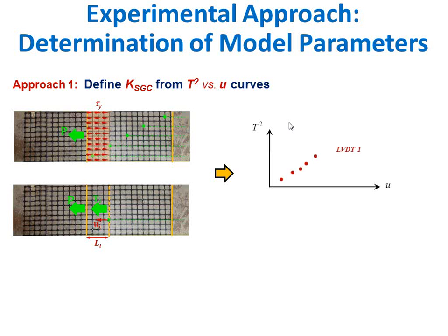What this formulation is telling us is that if we get the displacement at point 1, we are going to get the same slope if we base it on the displacement of point 2, and the same at displacement point 3. So to be really happy, not only do we need a straight line here, but essentially when we do a test like this, we're getting 5 curves. And all those 5 curves, if our assumptions are acceptable, need to be the same.